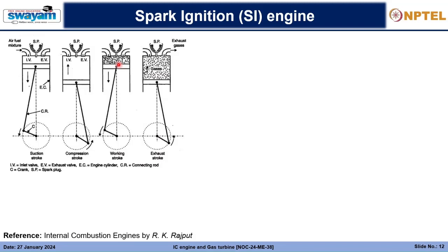So in four stroke engines, basically two rotations of the crankshaft complete one cycle, right? Here, at the starting case, it rotated once and ended the compression stroke. Again, from here it rotates again and comes back here.